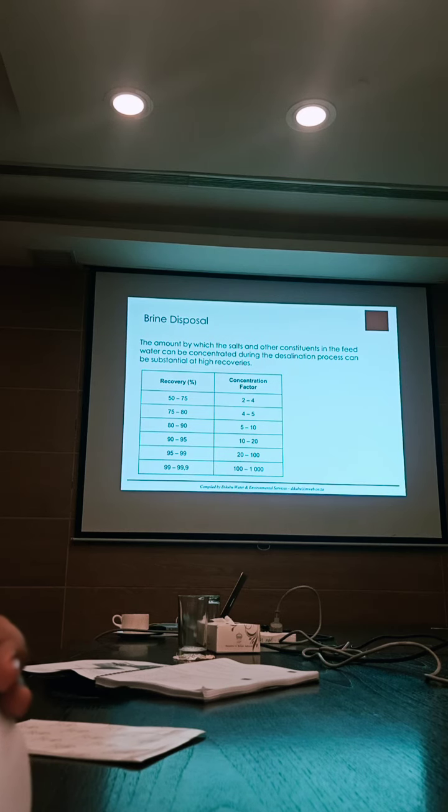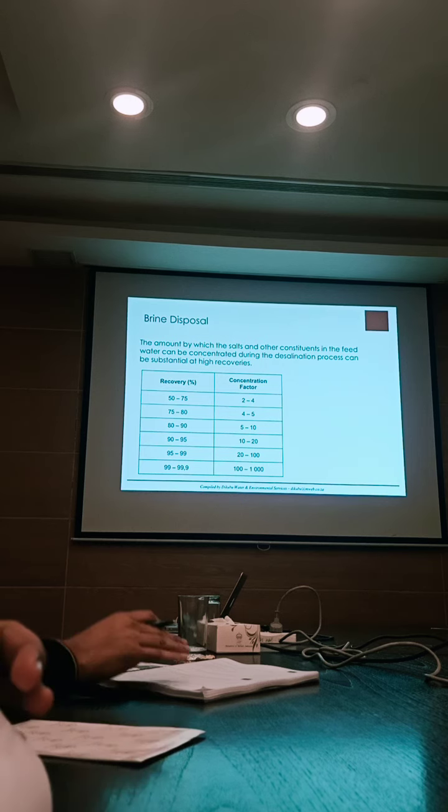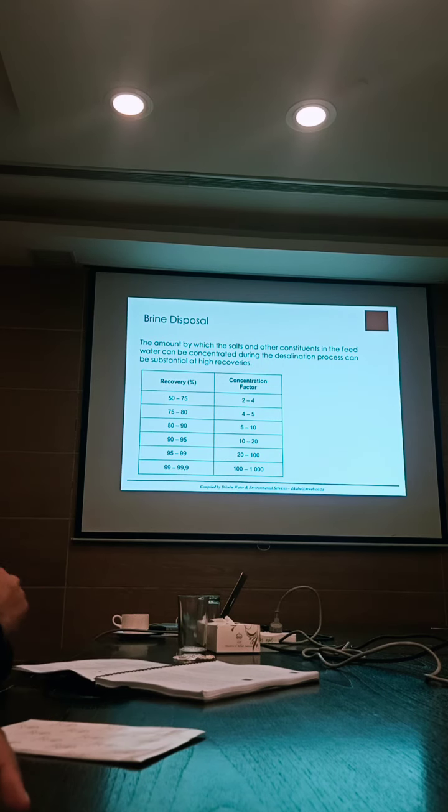Not only that, your corrosiveness, because you've taken all the salts out, becomes a water quality issue from your stability point of view. And then you can't go add chemicals to stabilize it, because you're going to affect the taste. So it becomes tricky from that point of view. So they tend to rather make up a certain amount from drinking water. Industrial application is different.